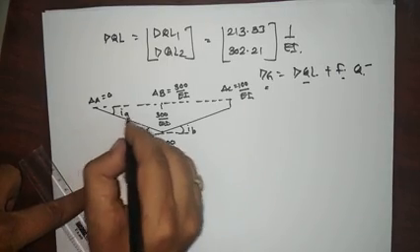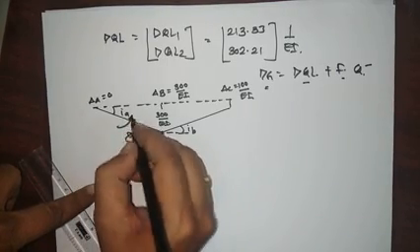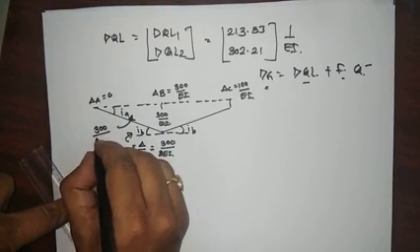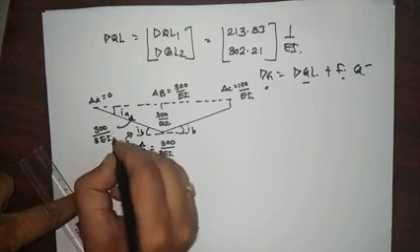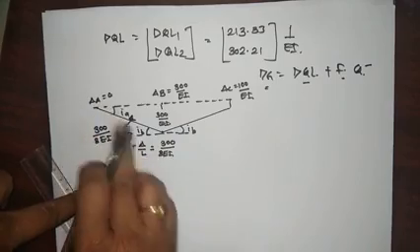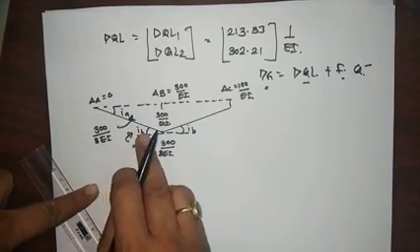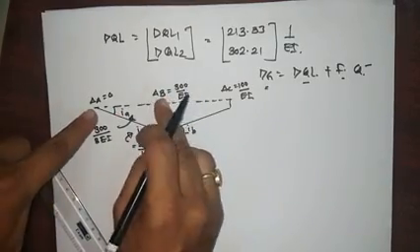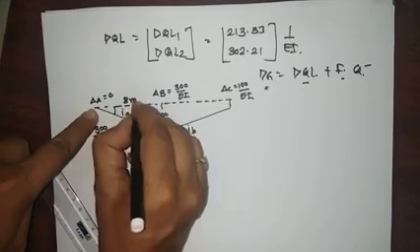This also is the same, that is 300 divided by 80, because the formula is delta by L. The slope at A and B is the same, that is this delta divided by this length, that is this 8 meter.